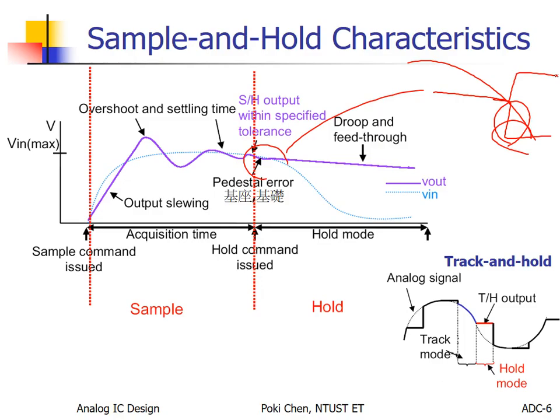So after turning off, you inject holes and electrons to the output, and hopefully you can balance the holes and the electrons. But that is only in theory. In practice, how to handle this? Usually we still need to apply a dummy switch. I told you already.